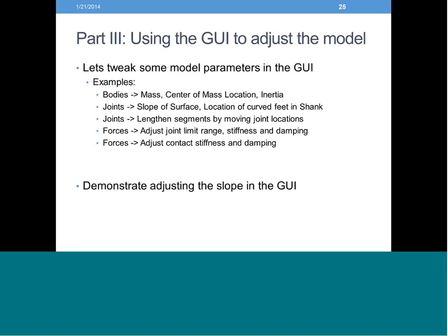You can change the range. When do those come on? You can change the stiffness and damping of those actuators when they are on. You can also adjust the contact stiffness and damping of the forces.